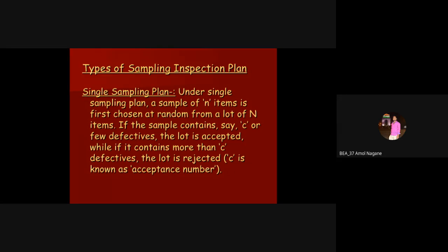From the 30 samples, a minimum of 50% must be good, so 15 of those 30 should be good. If 20 or so are defective, which is more than 15, we have to reject the lot. This is the value that is decided. Now 30 is the sample, and 50% of it is 15, so 15 products will be the C value. This is very simple single sampling.